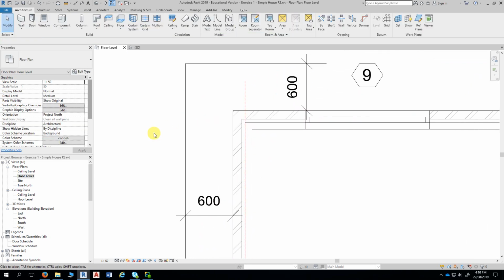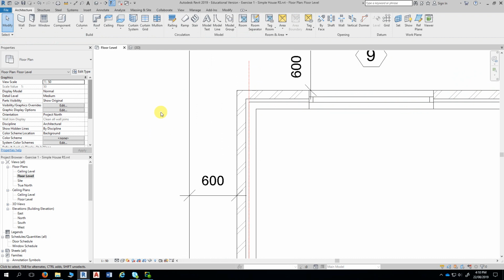I'll get in nice and close. So when we talk about the core of the wall, or the core boundary, see where the reference plane is running through? Just off centre. Yeah, it's actually the core of the wall in this case is running along the timber frame. Okay. On the inside of the timber frame. On the inside of the timber frame. So that's the core of the wall in this case. Now the other core boundary,